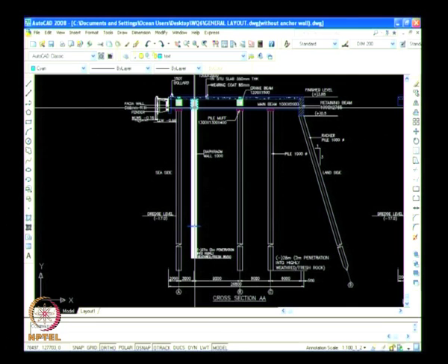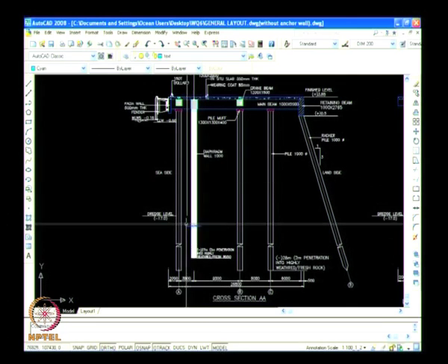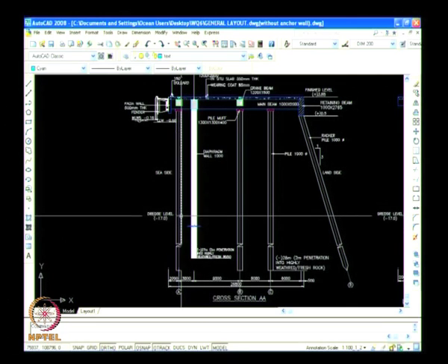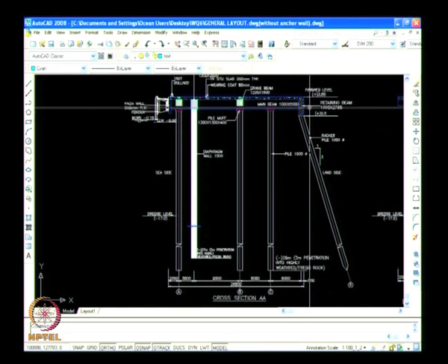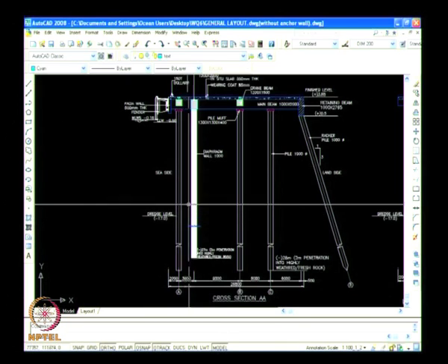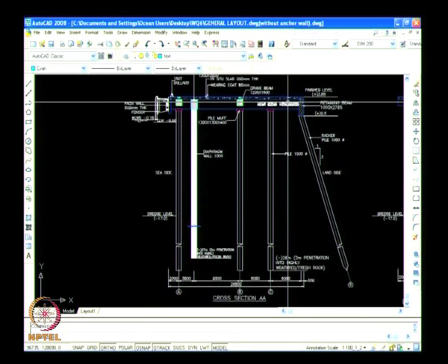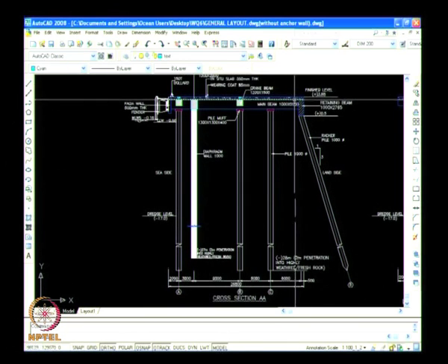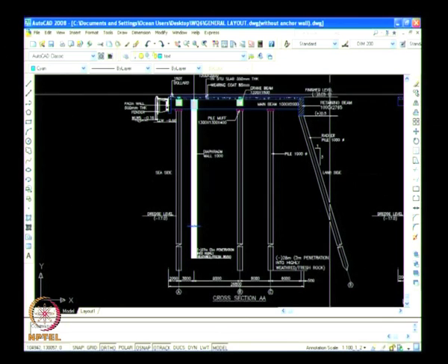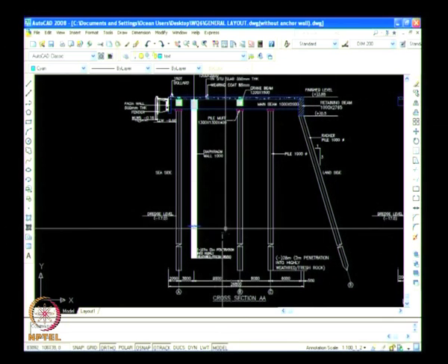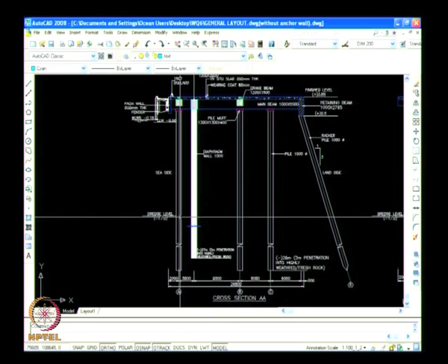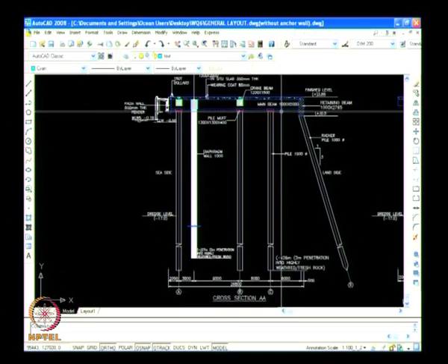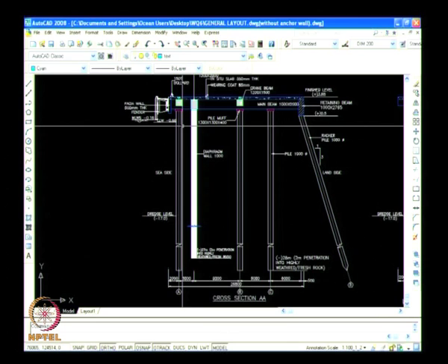One of the reasons we want to go for this alternative is there is an active edge. The active edge is here, it is a clay soil, so the active edge will be a 45-degree line. If we take a 45-degree line over this, it will be within the deck, so that any surcharge load coming here will not give any active earth pressure. Active edge means the soil will collapse when the diaphragm wall is moving like this. So for that reason we want to keep